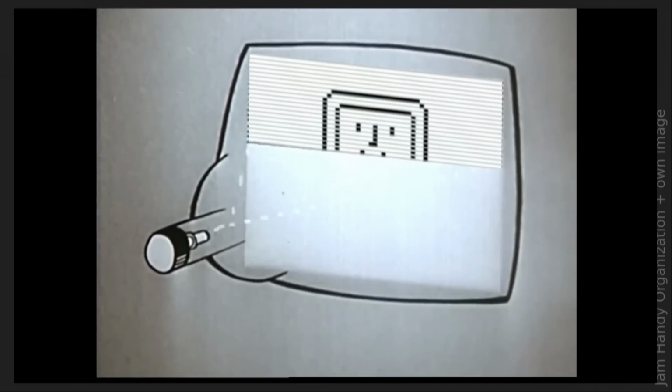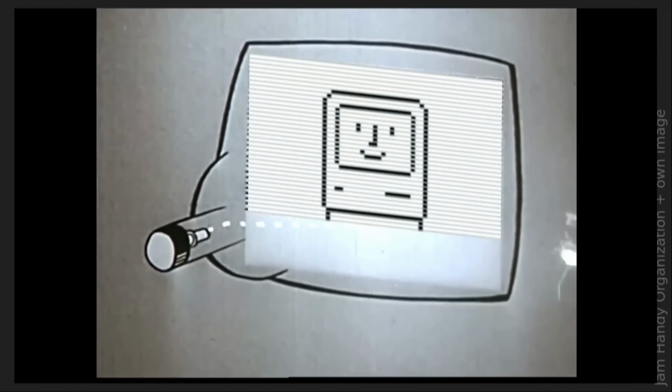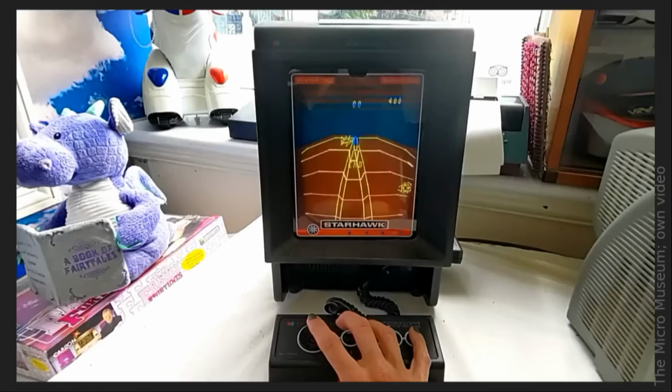Right, so CRTs for display in general now, not just scientific experiments, and the problem we face. Lots of people are well familiar with the kinds of CRT displays that draw a picture by scanning the beam across a series of horizontal lines while varying its intensity to make light and dark patterns. This is a raster display, and any sustained image has to be completely redrawn many times a second, since phosphor never glows for very long. This is why CRT TVs and monitors can seem to flicker.